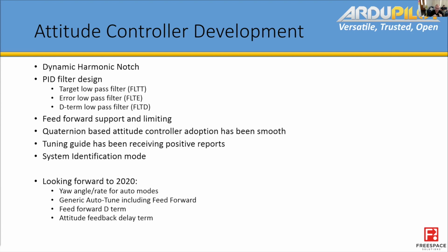It's funny, if you move quickly, you don't see this noise, but if you move slowly, you see this sawtooth thing in the error target as it tries to move up to the next increment on your RC input. And you don't see that in auto mode, for example, where we're actually getting a full rate attitude request.